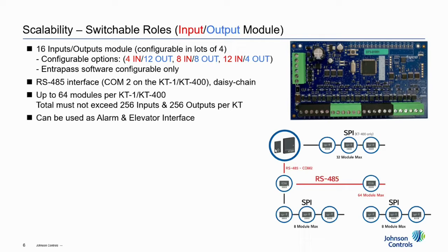Okay, you need to buy new module and perhaps power supply. This will lead to project delay. Whereas with this module itself, what you need to do is just to convert those interfaces assigned to outputs to inputs, and you are able to connect additional input devices. So that is the magic on this module.